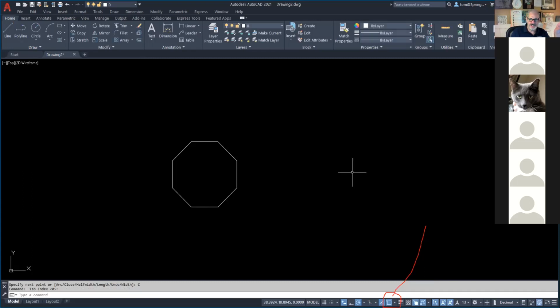Now, once those are on, the next thing we are going to do is draw diagonal lines across this. So how do we do that? Well, we start our line command here. When I start my line command, I'm going to bring it right here, and a certain object snap is displayed. What's that object snap that's displaying right there? Endpoint. And what is the shape associated with it? It's a square. That's exactly right. So we're going to click here and pull it down, and we really can't go diagonally, so we're just going to do the best that we can. We'll just click there.